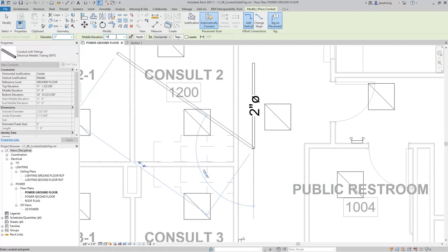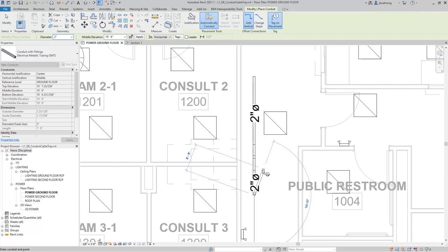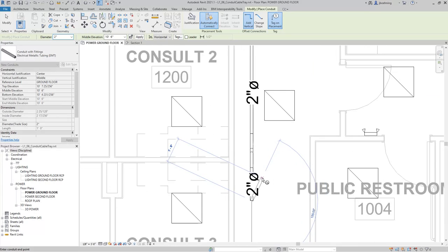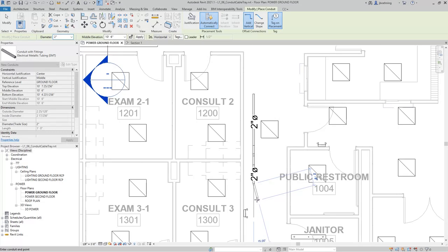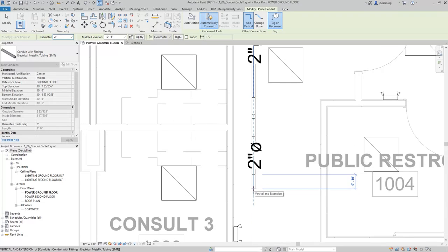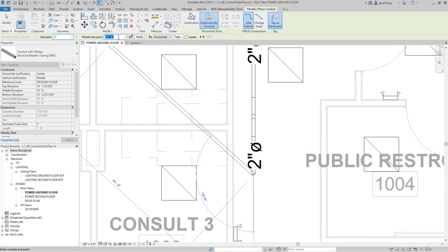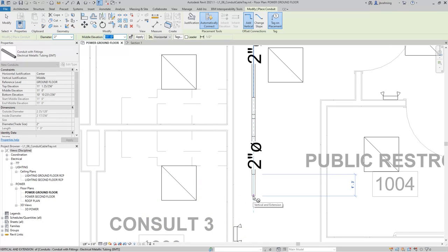Or in some cases, if it was too small, you may not ever get that option to get it to place correctly. But in this case we did. We had enough room. 6 inches was enough to place our fittings there. But when you have that cannot place option like we have right here, that means there's not enough room for those fittings to be placed.